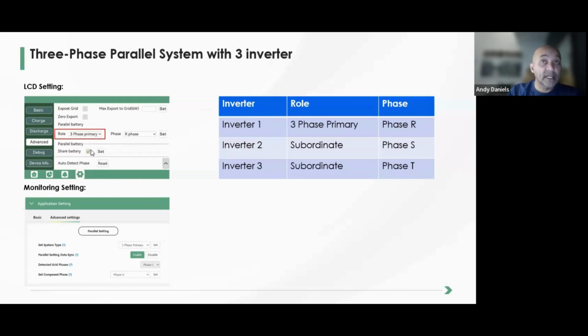All right, and then if you are setting up your bank with a shared battery, then you've got to set it here. That's also critically important because it allows the charging authority from the inverters to know exactly that it's a shared bank, that they will be controlling one battery bank to charge and to discharge. I like using a shared battery bank because you might have a situation where you have one phase that is quiet or underutilized, and you have one phase that has a higher load capacity. Then it's got access to the whole battery bank.